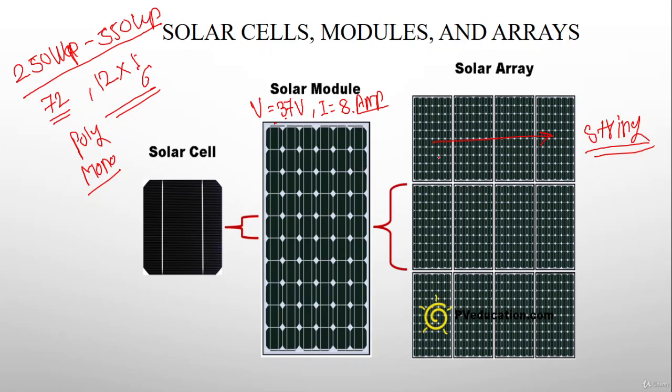But before that, whenever we join solar panels in series combination, we take the positive and negative terminals of the corresponding solar panel, and connect the negative terminal to the positive. Simultaneously, we keep connecting the negative to the positive. The connection we are doing is called a series combination. Series combination is used to increase the voltage, but the current remains the same.